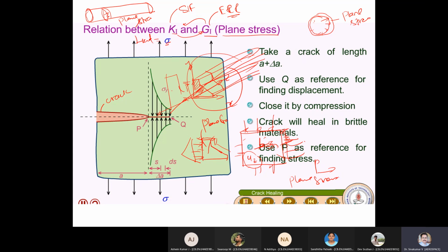It is not possible, because the structure must have the appropriate boundary conditions; only then can you convert it into 2D or 1D. Otherwise, it is 3D only. When you go for 3D, you have to solve complex mathematics with six equations and 6 unknowns, whereas in 2D there are 3 equations and 3 unknowns, so your solution will be quicker and easier.